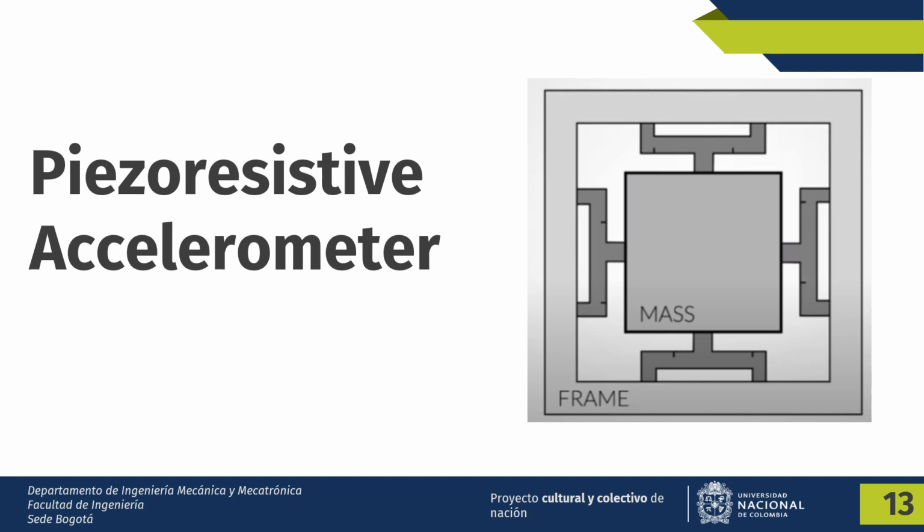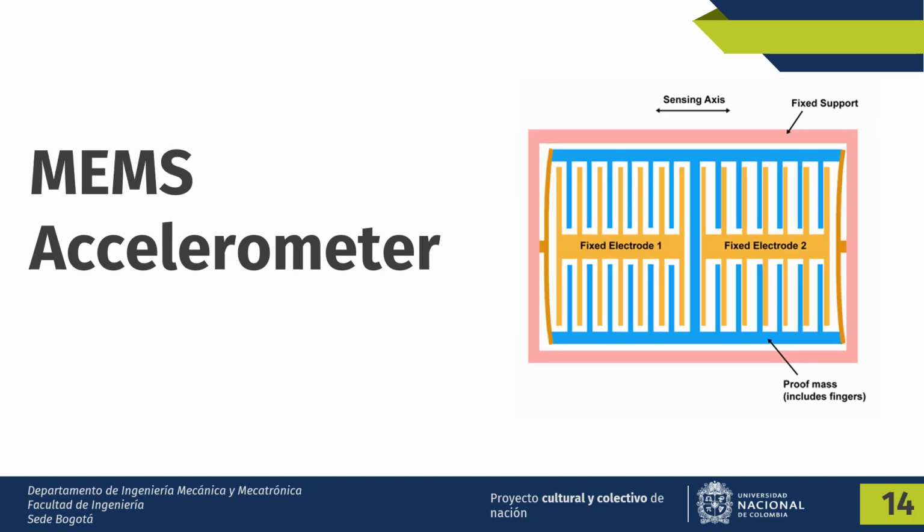Similar to the piezoelectric sensors, a piezoresistive accelerometer has a material that changes its internal resistance when deformed. This change can be converted to voltage using a Wheatstone bridge.